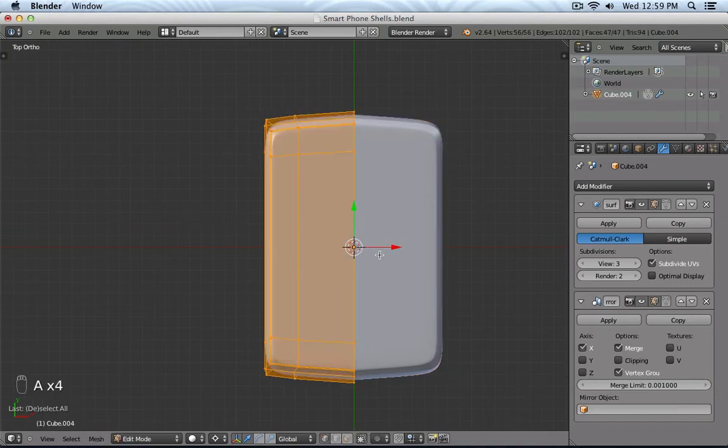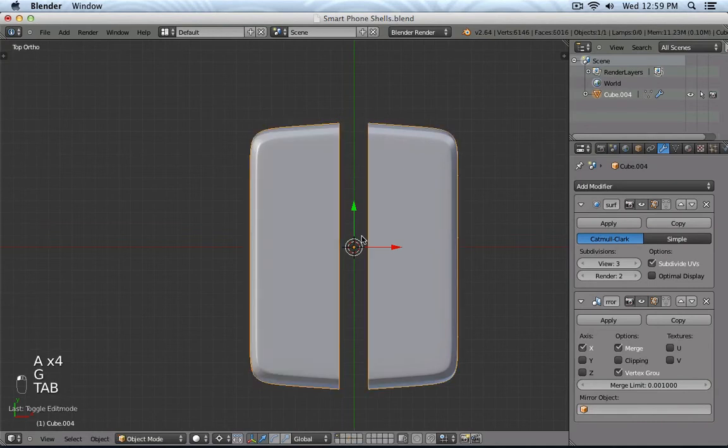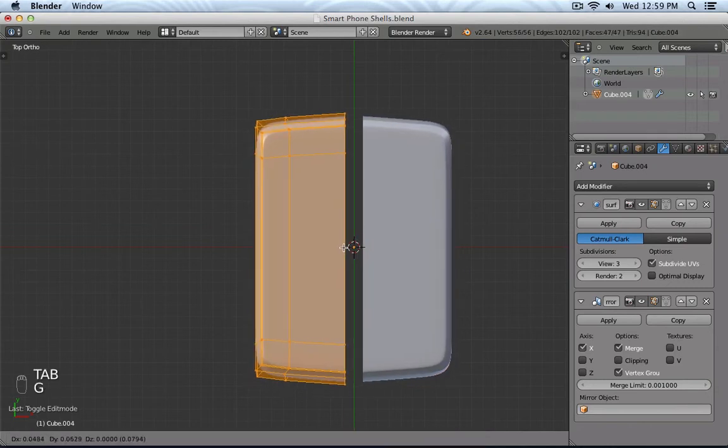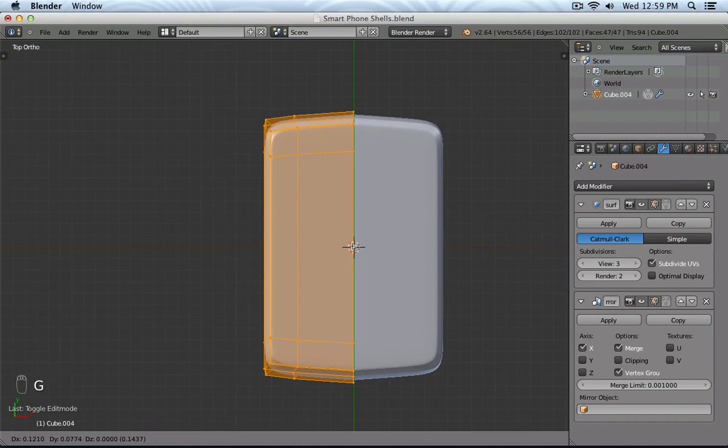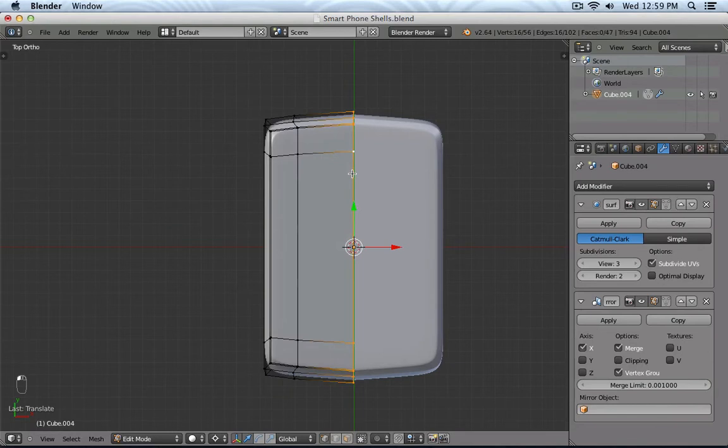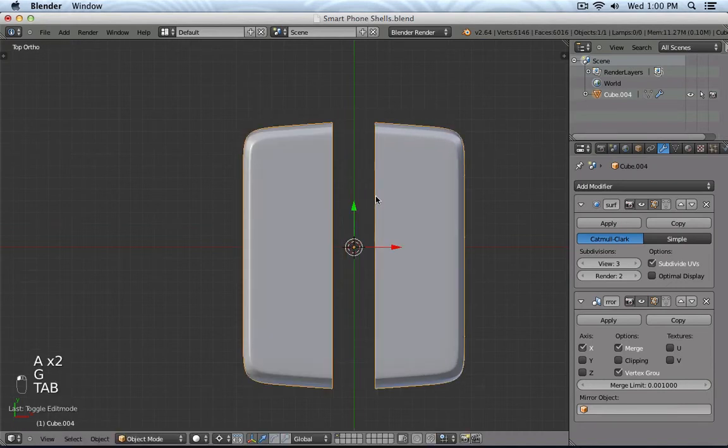Now let's say, well, by accident, you have your whole shell removed. Well, and you don't really want to change your shell. I mean, you could go in and try to position it correctly, get very close, and then at this point, snap your mirror cross section to the object center point. Not really what you want to do, because that might change your design. But maybe instead we could snap the origin point now to my shell.